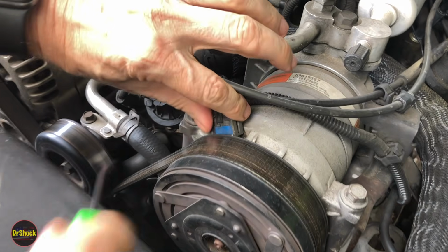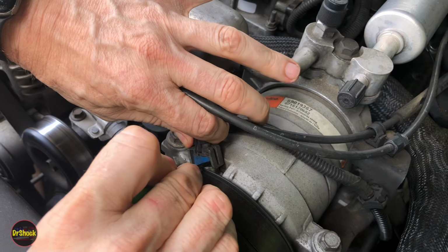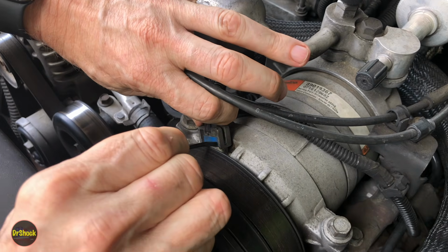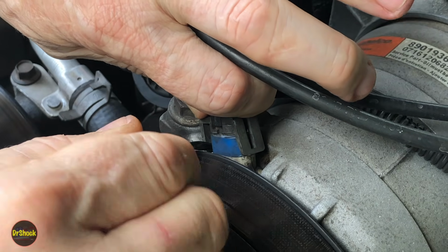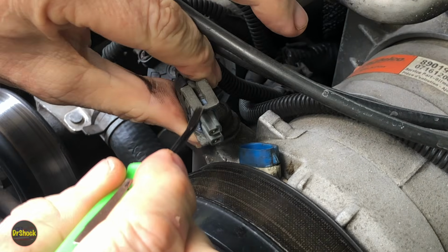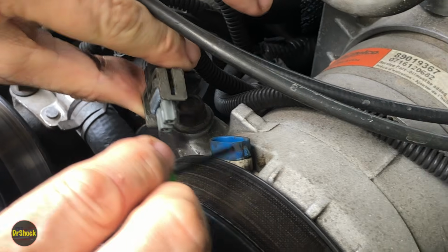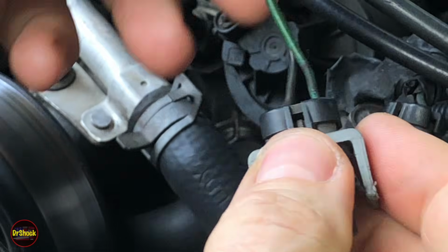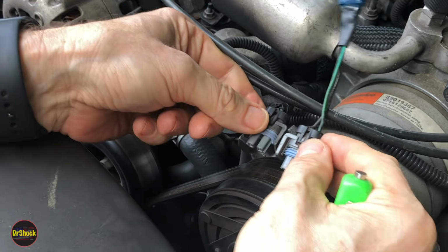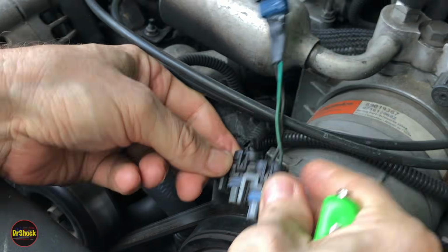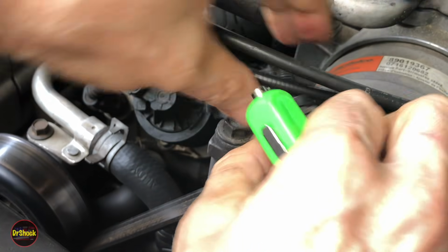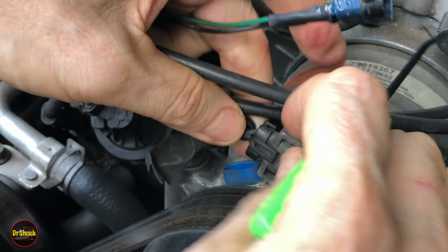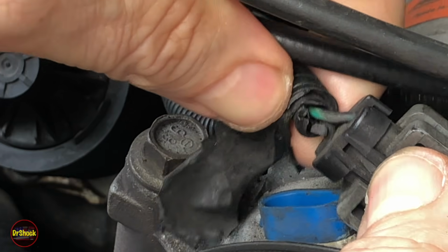I'm going to disconnect this wiring harness plug for the electromagnet. What you've got on here is a couple of little prongs on the side. You can get yourself a little mini pry bar like I'm using. You just want to lift these off gently and get them past these little prongs that you see here. What I use for this is my own little made-up harness of OEM connectors. So this is the same connector here, right? You've got a dark green wire supplying current and a black wire for the ground. That's what we see on the original as well, once we get some of the dust off the back here.